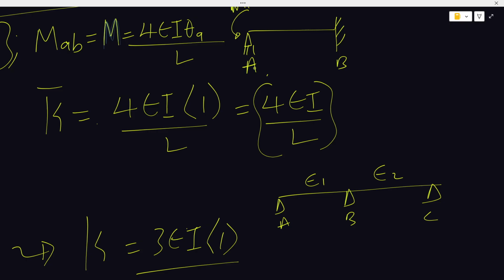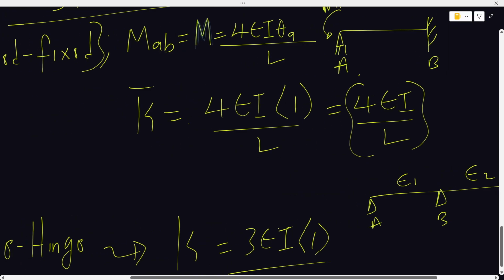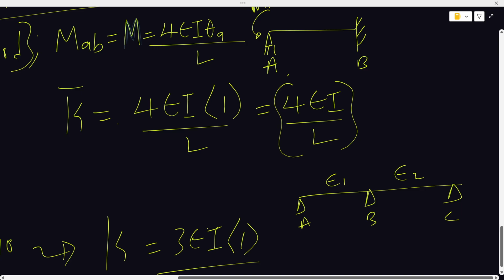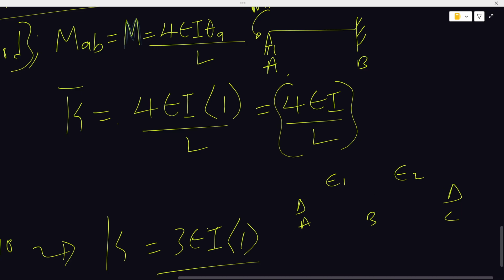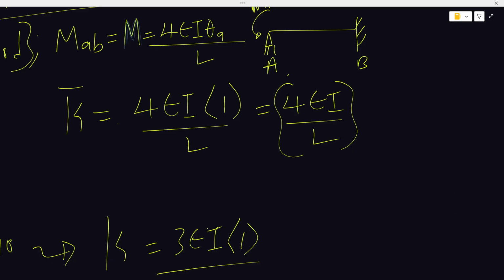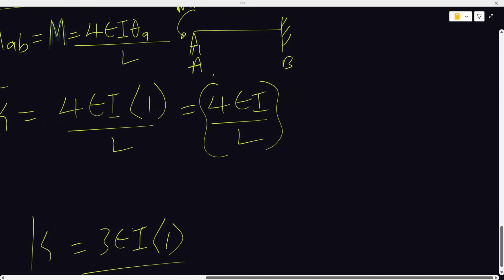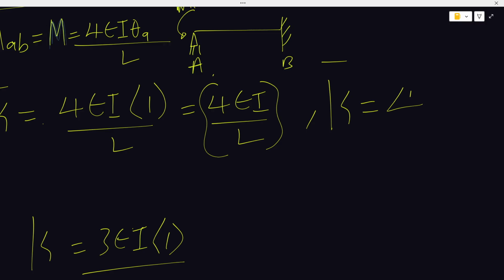But if my E is now the same, it doesn't make sense for me to be using any formula that has the elastic modulus. So what can I do? There's something called relative member stiffness. I don't need my E anymore, since all my members have the same E. So relative member stiffness is telling us that we should divide our K prime by 4E, in order to eliminate E, because the Es are the same now. Do you get?